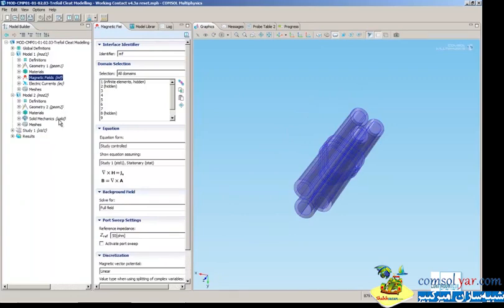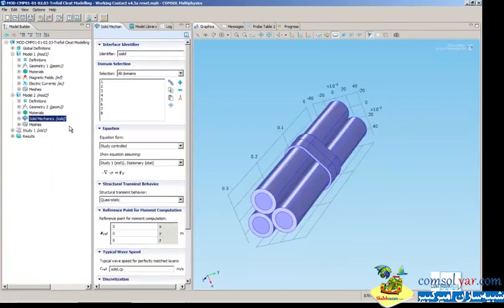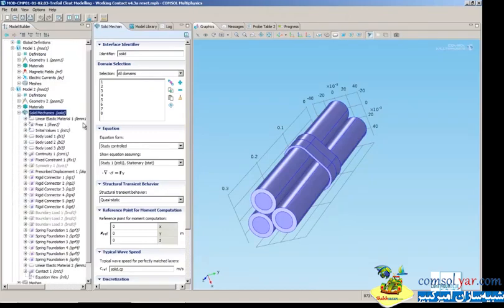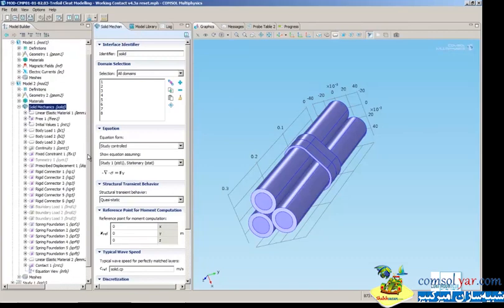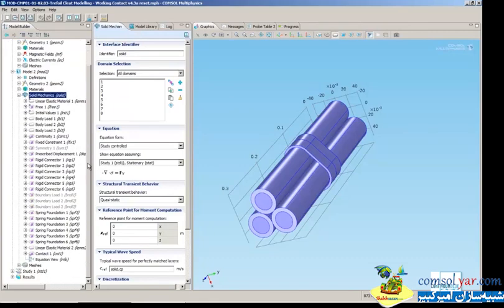The structural mechanics section makes use of nonlinear material models such as plasticity for the copper in the cable and steel cleat. Additionally, hyperelastic material models for the polyurethane sheets used to insulate the power cores.